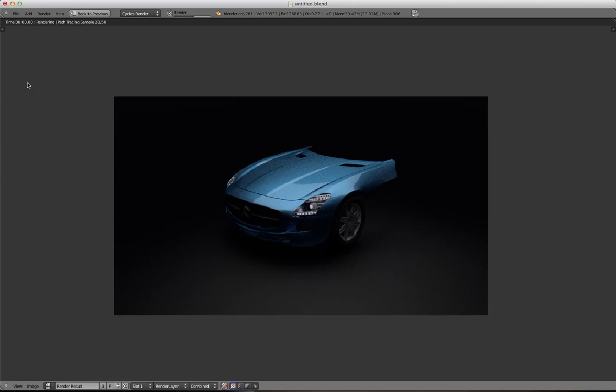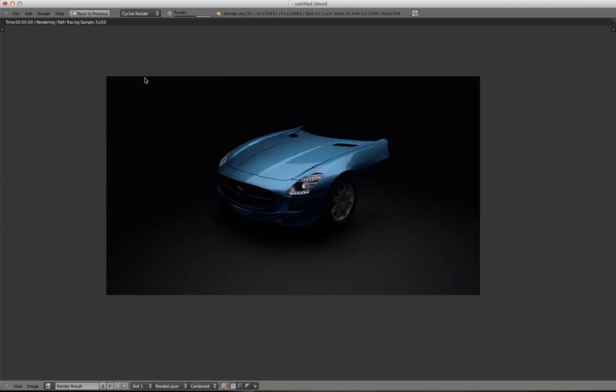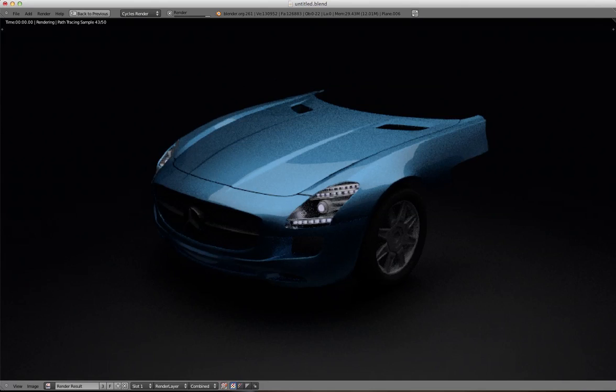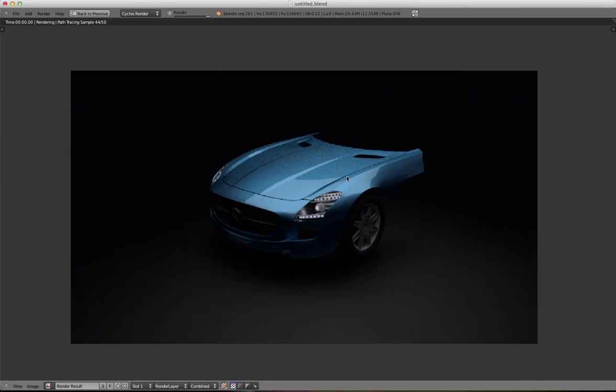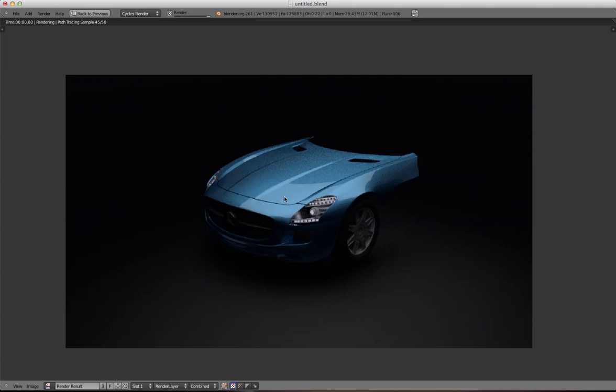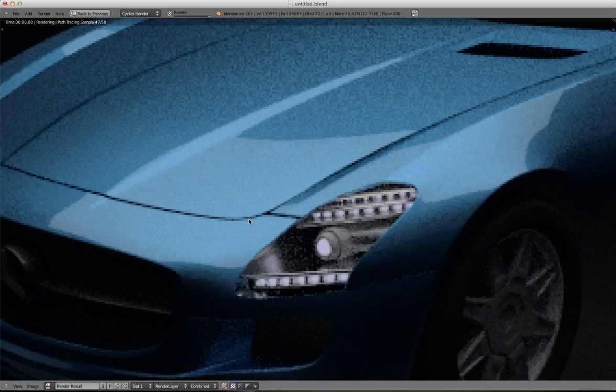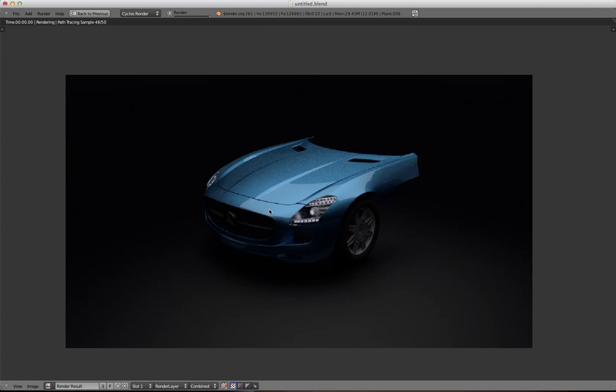So you add a first node, which is the scene output. So you get this image, the render, there in the first box, and then you can connect the first box with the second box. And for example, the second box could be brightness and contrast, and then you can change these values. And the third box could be the compositing output, something like that. And then everything that does is changing the brightness and the contrast of that image here. That would be an example for what you can do in the node editor.